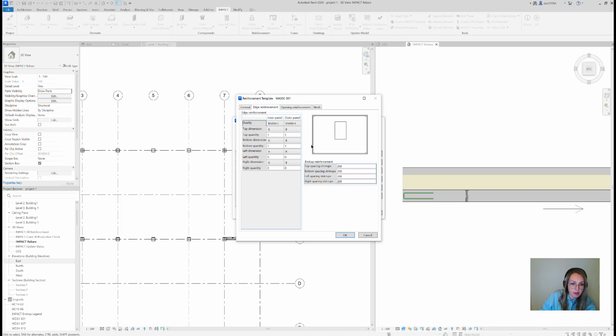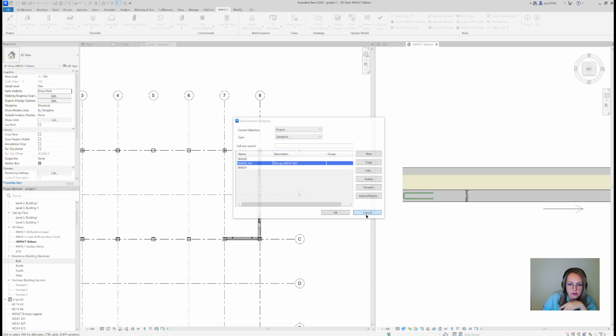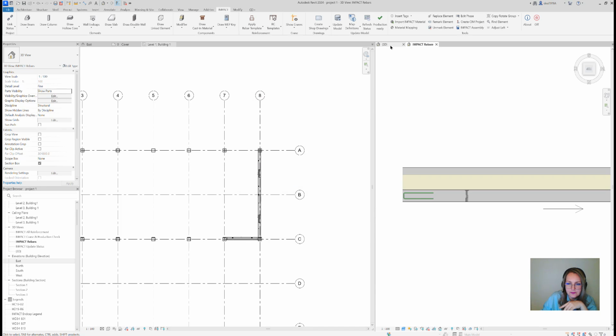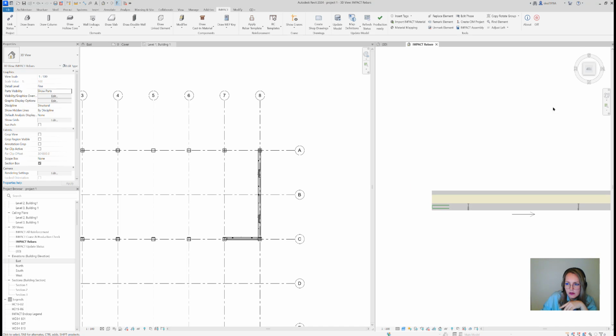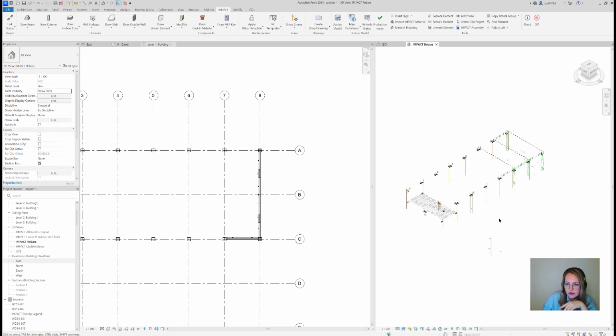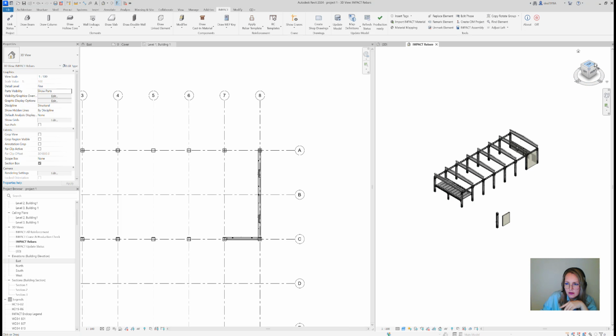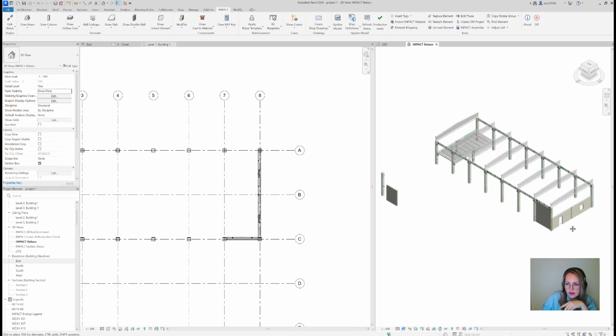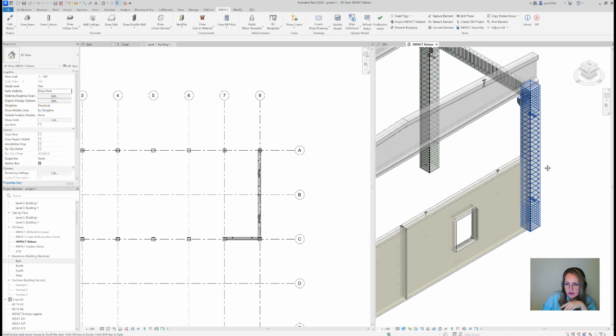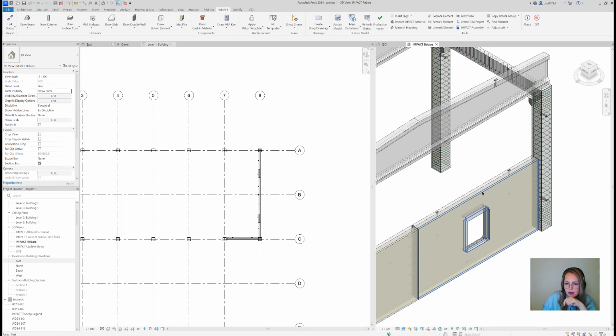So if you have this in cap added to one of the edges, let's say left or right, you add a stirrup defined in the in cap, 200 with 200 millimeters of distance. Let's see how it works. You probably want to see it in this way. Let's see. I think we can do it directly in 3D view.